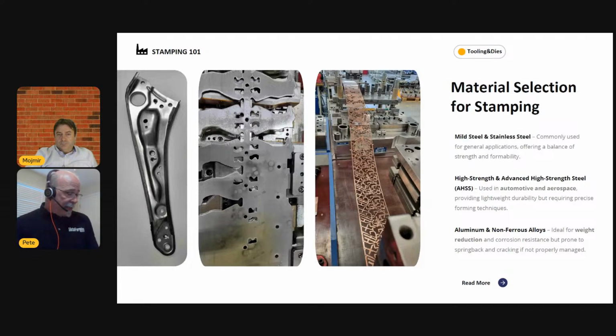Now, that phase I mentioned was martensite. Where else have we heard the term martensite? When we heat treat tool steel, right? We heat treat tool steel, we austenize it, we quench it. And what's the microstructure that we have? Untempered martensite. Martensite is very hard, very brittle.